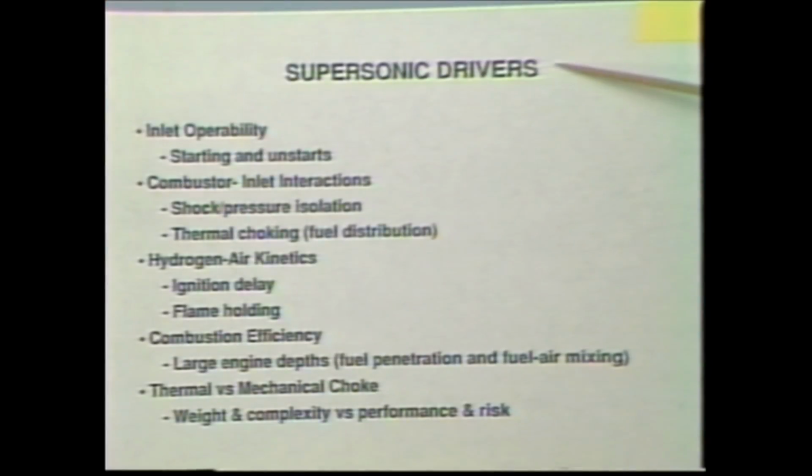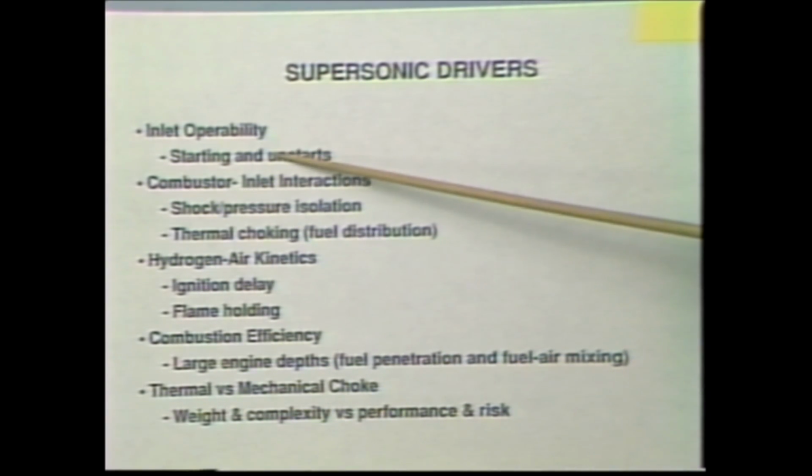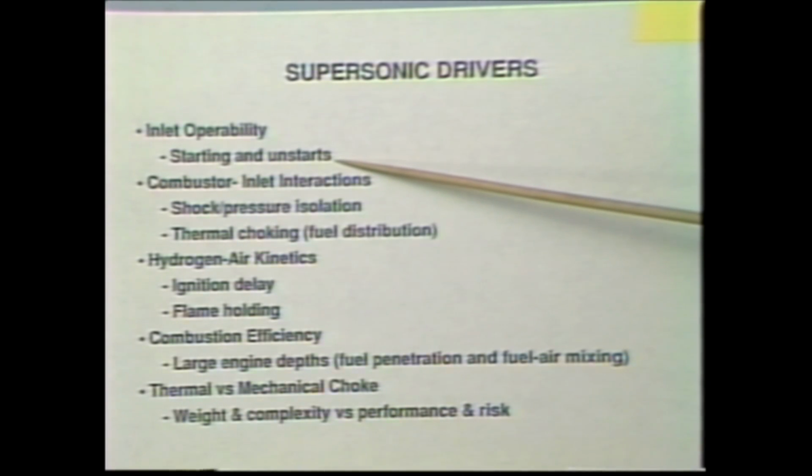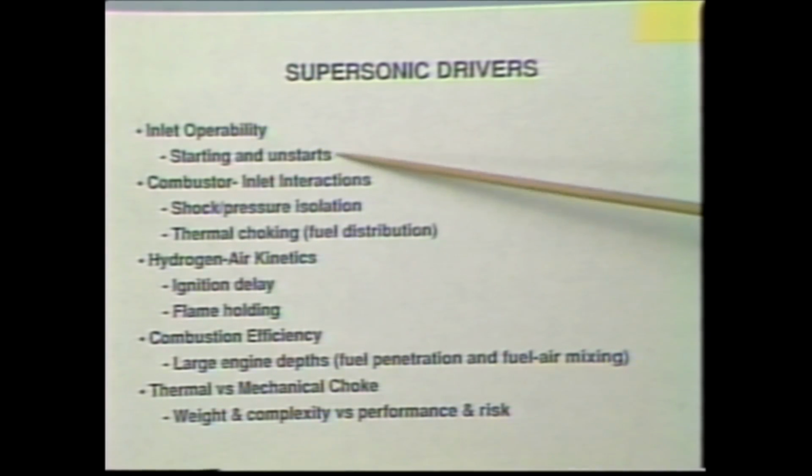I'm going to move on to supersonic drivers. We've gotten through transonic now. Supersonic drivers are inlet operability. That means starting the inlet. We talked about requirements to start the inlet. Contraction ratio cannot be too large or it will not self-start. You have to geometrically do something, or dump air, or have blowout doors or something like that to start it. And then unstarting, that was also mentioned.